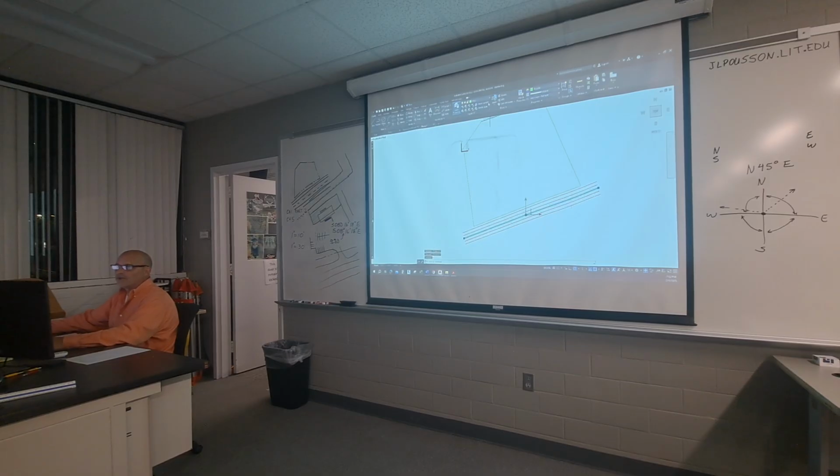This one is the center of my roadway. We're not gonna use a center line. Remember, those of you that have driven on a road or rode on a road, you know it's not a long dash, short dash, long dash, short dash. It is a hidden line type for the lane. So you can go through and start building your drawing based on that.